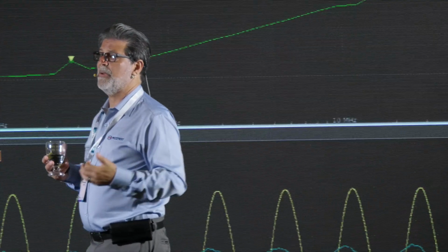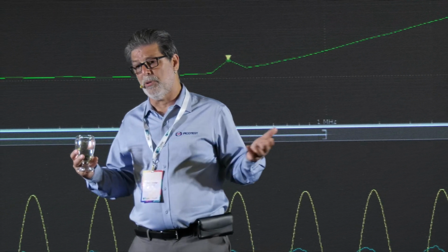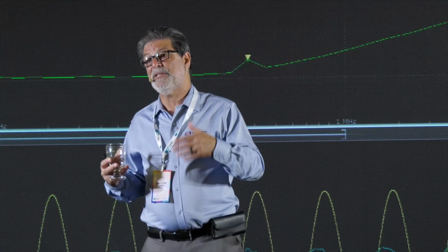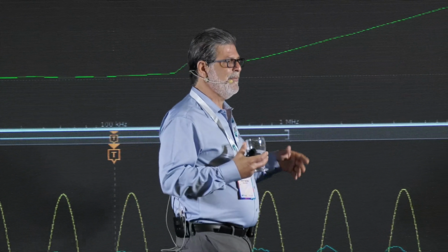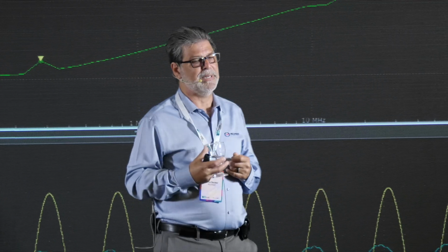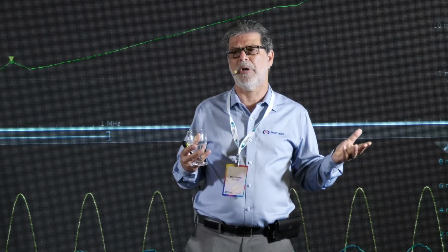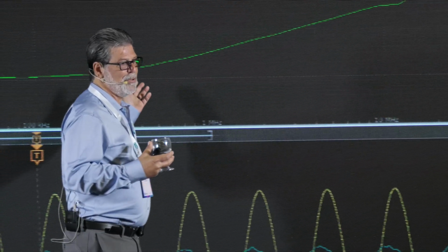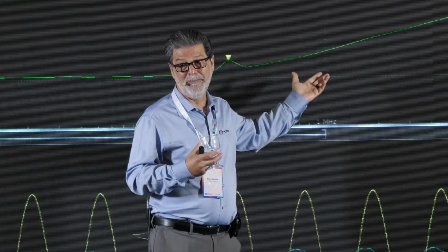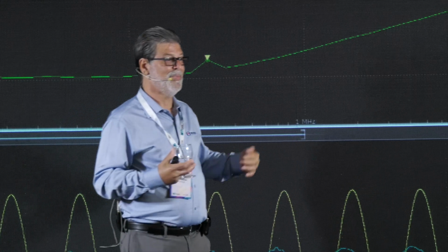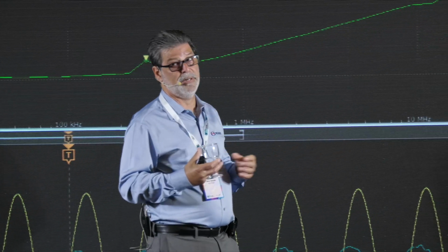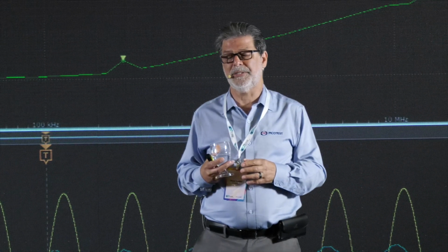If we want the impedance to be flat, it says that the Q must be equal to or less than 1. That means the square root of L over C divided by our target impedance must be less than 1. If I rearrange that equation, you'll end up with C equal to L over R squared. I talked about why we want to know this excess inductance, because that's L. C is equal to L over R squared. If I cut the resistance in half, it takes 4 times the amount of capacitance to absorb that inductance.